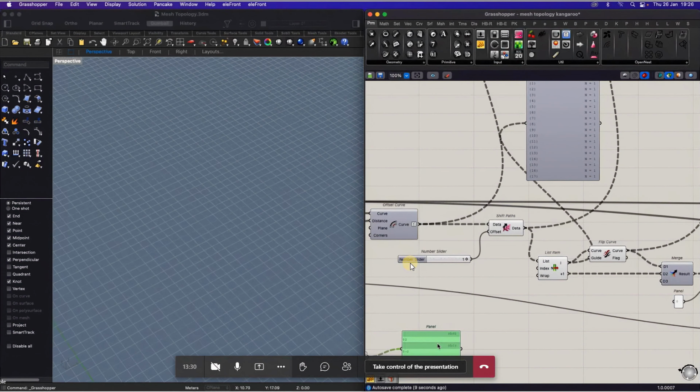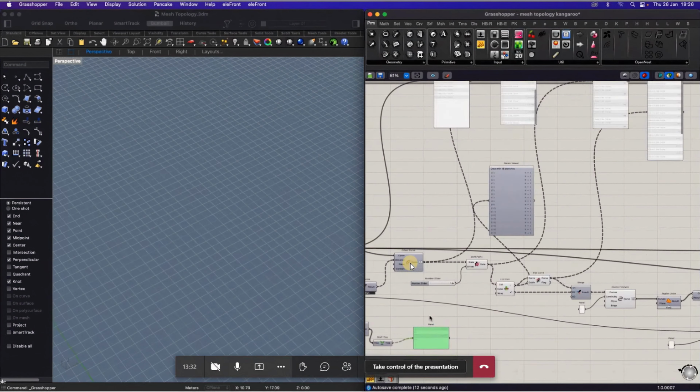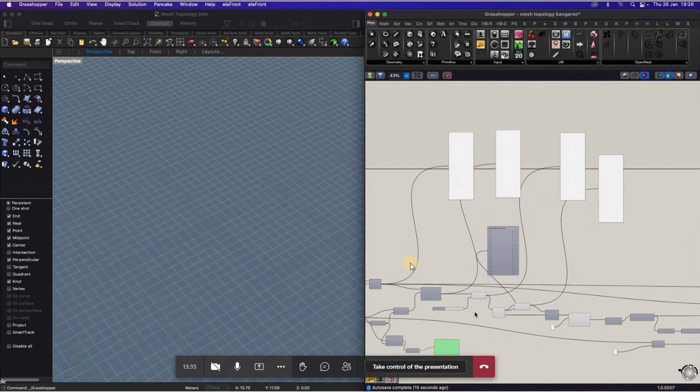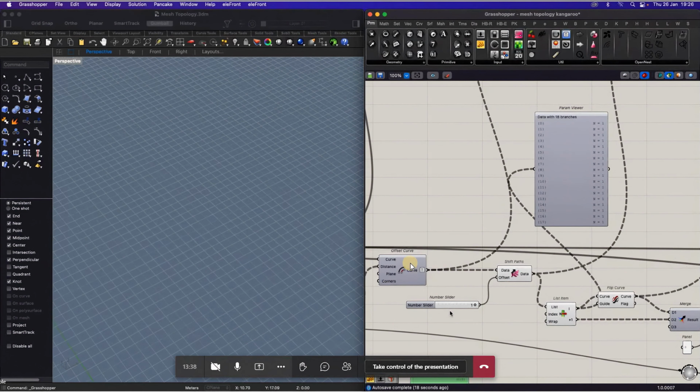Does Dynamo also have flatten, or is it some other way? Dynamo has a flatten, yeah. But the way grafting works in Dynamo is there are things called levels. It's kind of more complicated. You have cases where you've got lists of different lengths. Maybe there's a list that might have 4 levels of nesting, and another list might have 3 levels of nesting. You need to match those lists sometimes, and to match them, you need to look at the whole list and pick what level you precisely want them to match at.